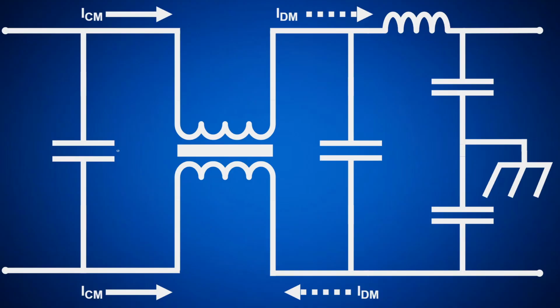Another option we have for reducing the differential mode noise of a digital circuit is to increase the loop impedance. The reason why this works to reduce our EMI is that by increasing the loop impedance, we will reduce the loop current, and as you know, that has a direct impact on the radiated emissions. Now, I'm sure you're wondering, but won't increasing the loop impedance have a negative impact on the performance of the digital circuit? After all, we just got done talking about how having too large of a resistor can negatively impact the digital circuit's functionality. And you're right about that, which is why I use the term impedance and not resistance, because we want to adjust the circuit's impedance, more specifically the higher frequency currents that are flowing in the loop.